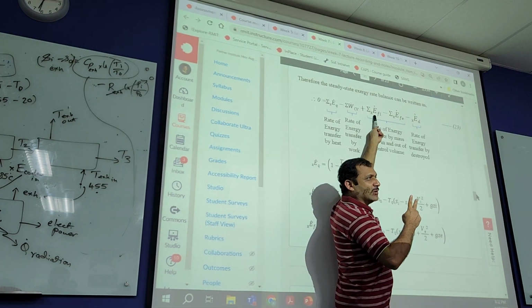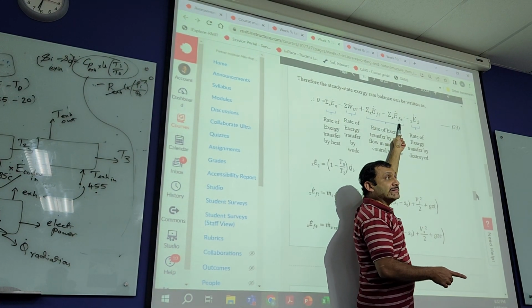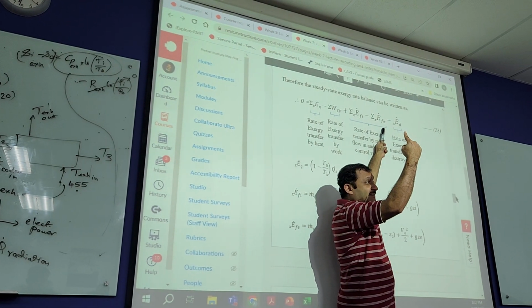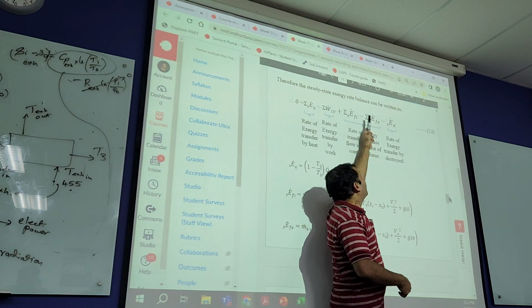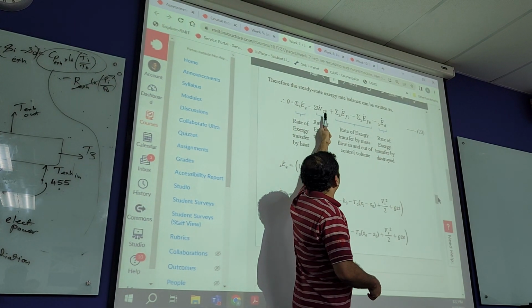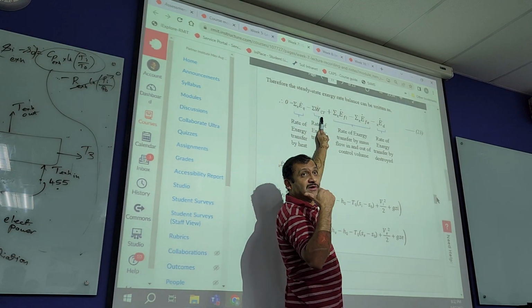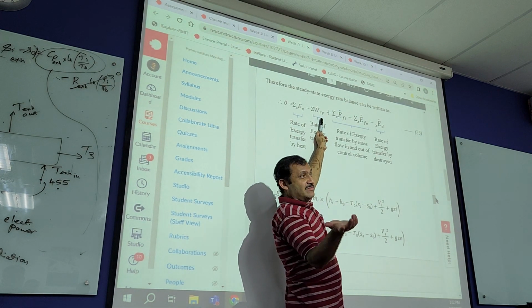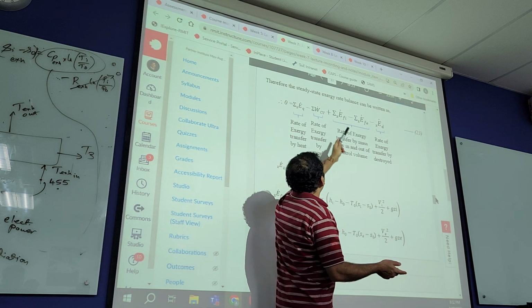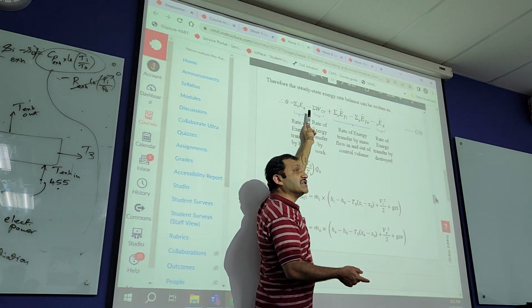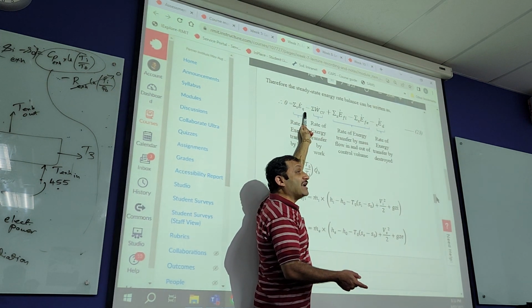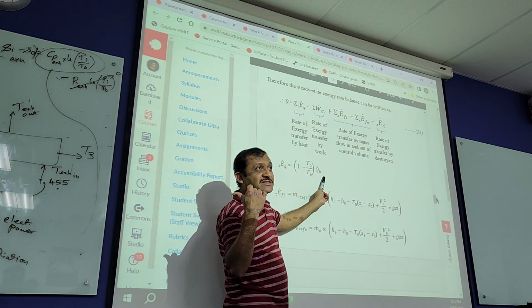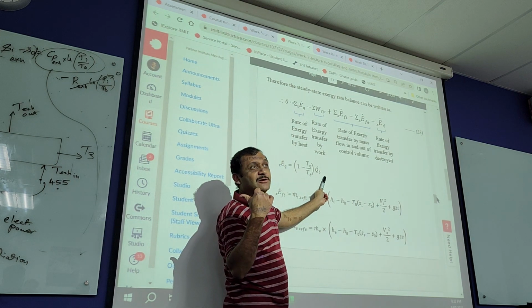Fuel going in, coolant going in. What is going out in the form of mass? Exhaust is going out, coolant is going out at 85. So that captures that part. Now, are we getting any work out from the box? Yes, electrical work out. Do you already have the total electrical output? You have. Now, are we losing any exergy in the form of heat? Radiation. Do you know the radiation heat? So that Q dot will be your radiation in kilowatts. Do you know that? Yeah.